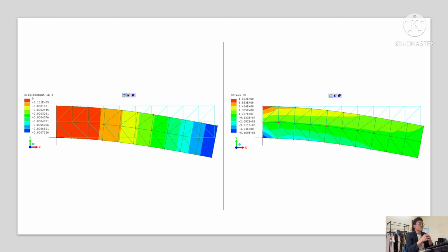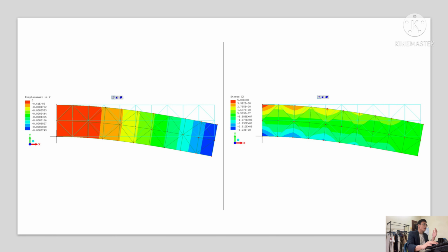As you can see in the figure, the beam experiences 2 types of stress at the fixed end. The stresses are compressive and tensile stress. These stresses are of the same magnitude but on the opposite regions from the neutral axis.